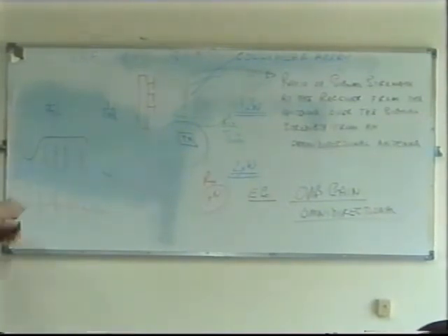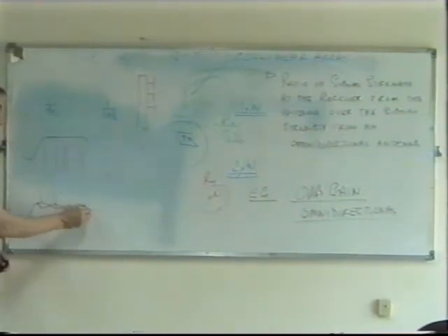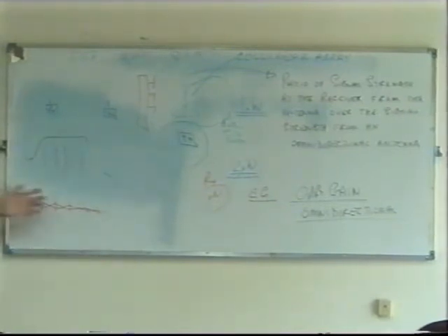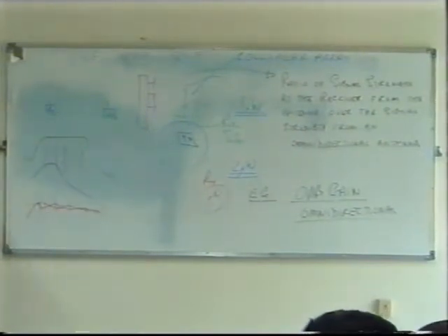Actually, the transmitter comes up on a cable, goes to the first dipole, and then goes to the next one crossed over, and so on. That's how it's actually done. Going to which element? They go into all elements. Basically, if you're, say, operating at the lower HF frequency, you're going to get more radiation from here and less radiation from there. If you change to a different frequency using the same antenna,